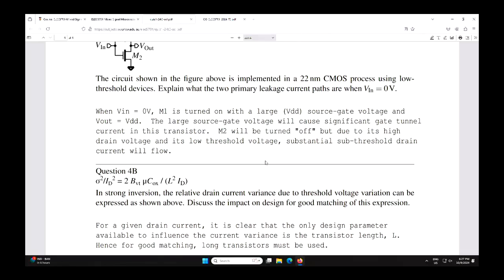Now, when you're in the design phase, and I think it's important to make that differentiation, in the design phase it's probably better to think about the transistor dimensions as being the free parameters, because normally that's how you drive the design. And you might have some specs to meet. You need to gain a certain noise performance.